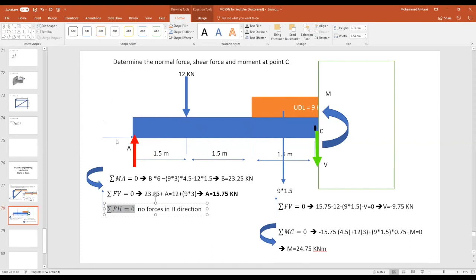So I'm acknowledging the information that, hey, I'm aware this is a hinge, but it is not effective because nothing is moving the beam. Similar to the whiteboard we had in the class. When it's fixed on the floor, it's always showing you that it's not moving. So there are no forces in the X direction. But when I push with a force in the X direction, definitely the whiteboard will start moving. So that's a difference.